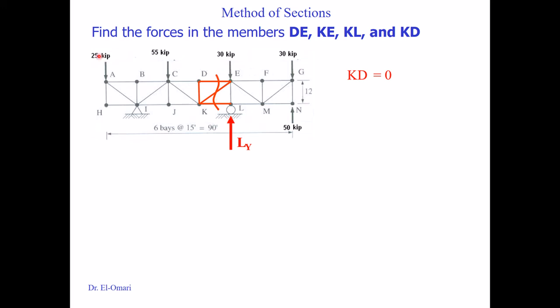So before we find the support reaction, that is part of the side that we would work with. You decide either side to work with. Always decide the side that is shorter, that has fewer external forces, that has fewer support reactions to work with. So we decide to work with the right hand side.